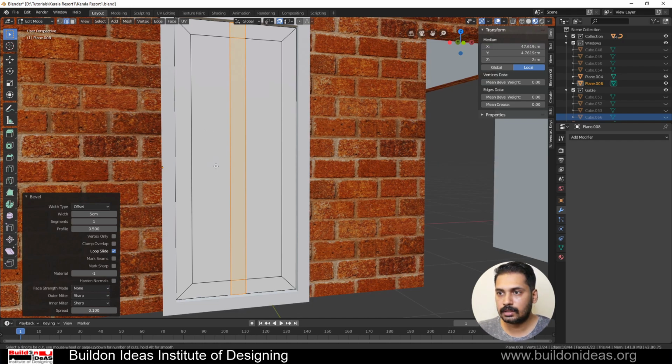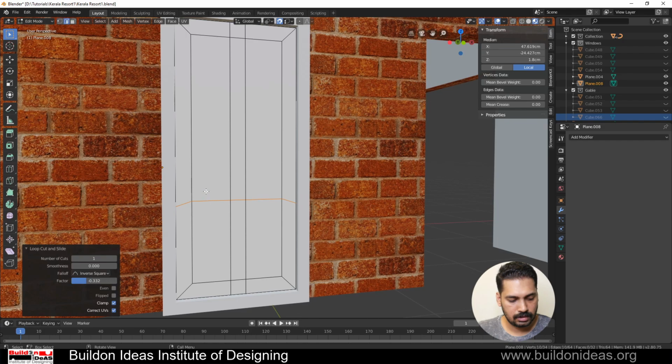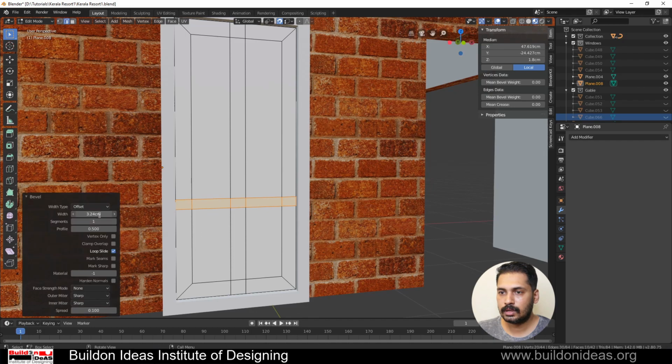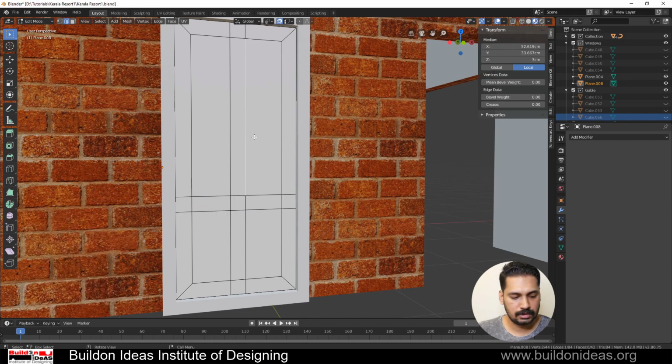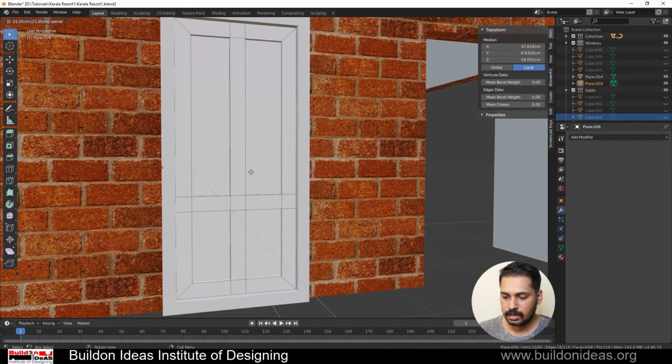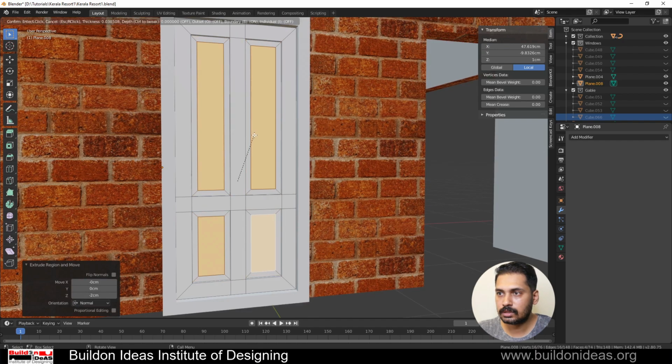Again I'm dividing this here, moving it slightly down, and scaling in Z direction 0 to make it straight, then right click, Bevel Edges by 5 centimeters. Now we have 4 segments here, so select these faces and give an extrude inside of -2, and then one more insert.